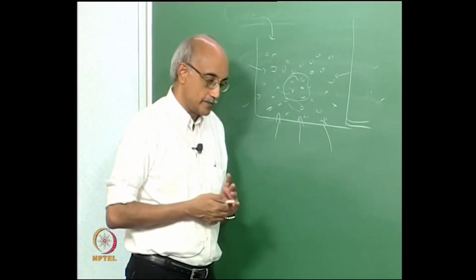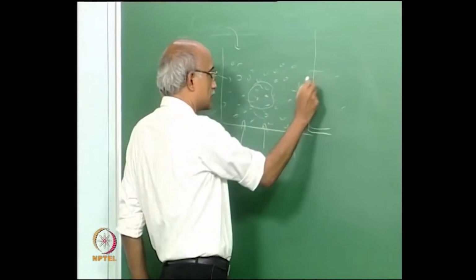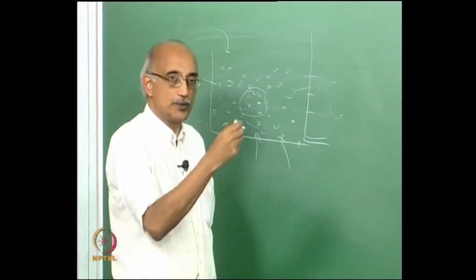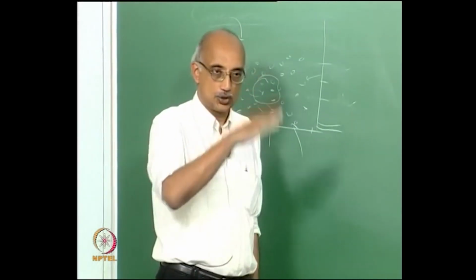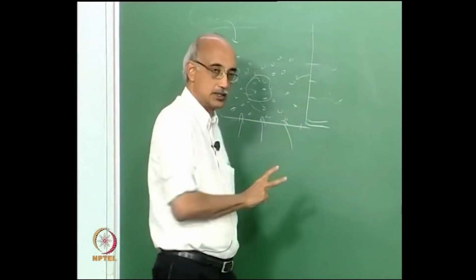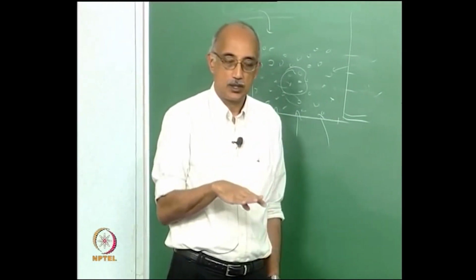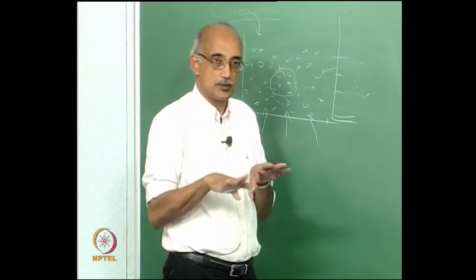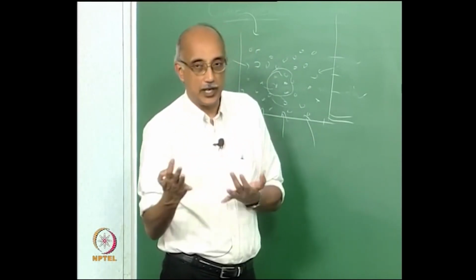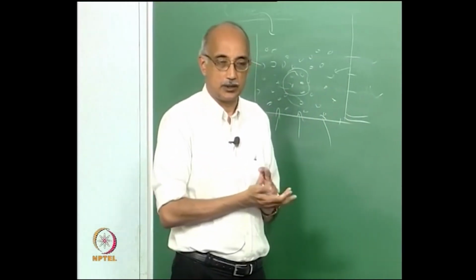So typically the approach that is used is to do your experiments around the perimeters, and you do your predictions for the entire stored material, and then you compare your predictions for the boundaries versus the actual measured data at the boundaries. And as long as there is good convergence between those two, you assume that because the model seems to be reasonably accurate around the perimeters, it is also going to be accurate in the bulk of the material.